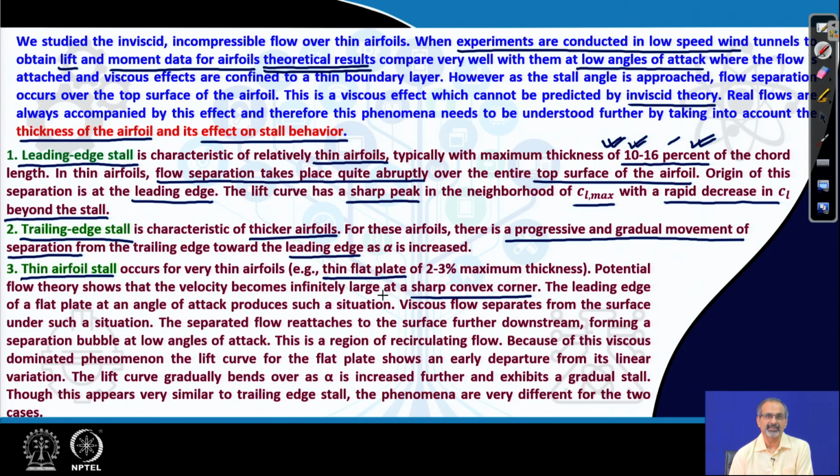So, there is a flow separation and formation of a recirculation zone. The flow generally reattaches on the leeward surface, creating a recirculation pocket or a bubble. So, we have a so called separation bubble at the lower angles of attack, but as the angle of attack increases beyond a certain point, it is unable to reattach at all,